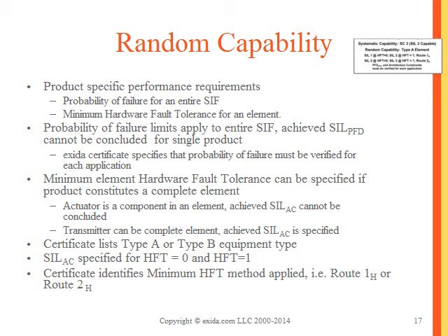But the entire safety instrumented function is going to consist of many different components. So the exida certificate simply states that the probability of failure must be verified for each application. We cannot tell you up to what SIL level this product will be able to be used because we don't know how often you do your proof tests, we don't know how you do your proof tests, we don't know what your maintenance capability is, we don't know what redundancy scheme you use, and so on. So from an exida assessment perspective, we can only tell you that you need to evaluate your probability of failure requirements as part of the entire SIF.